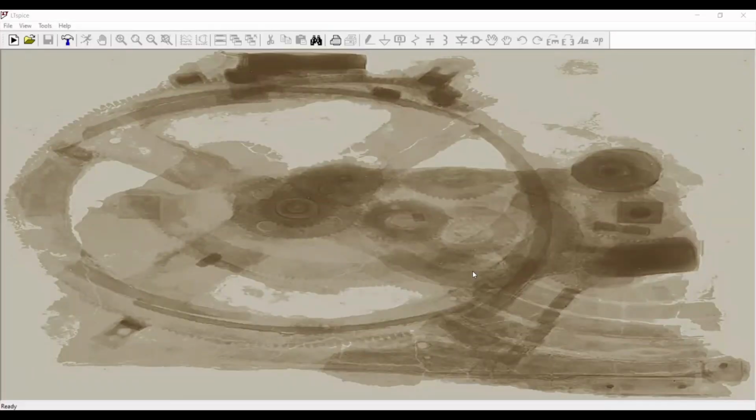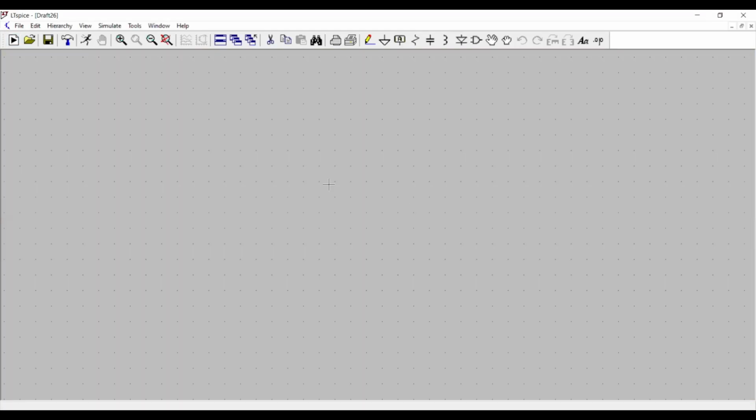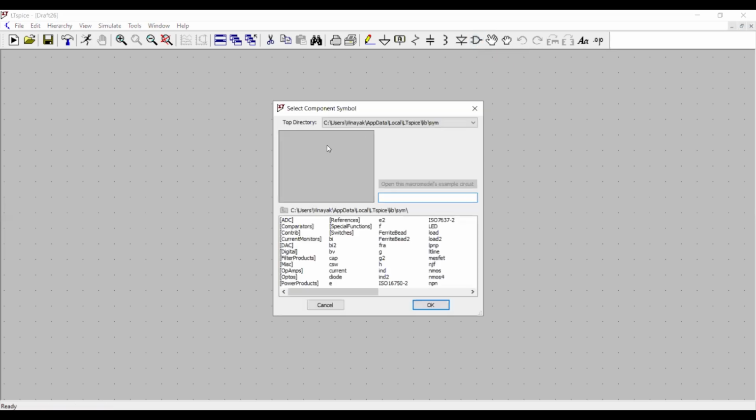Okay, all right. So in this module, let us understand how we can build a hardware for a current mirror circuit using two bipolar junction transistors. So here I have actually used the SPICE circuit simulator and the device libraries. So basically, I would click the new schematic right here, and then the screen gets open, and then I will click here the components where I will look for the components I want.